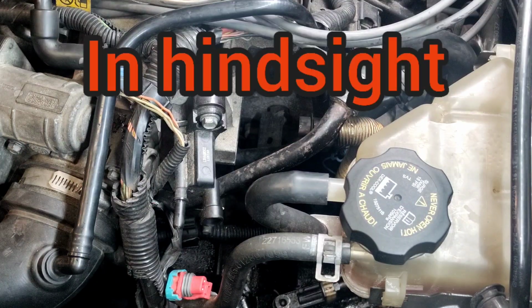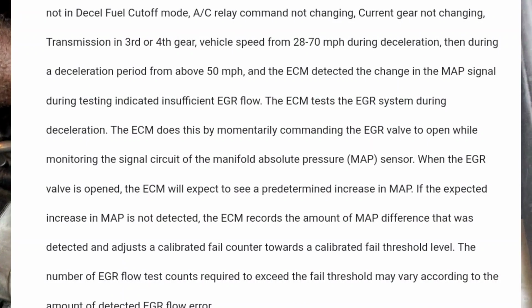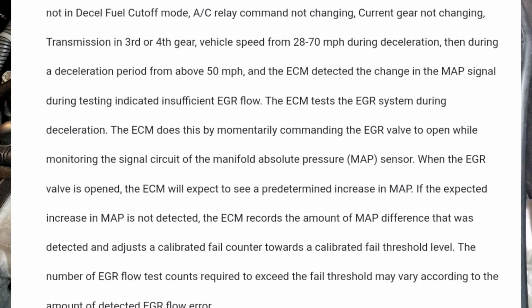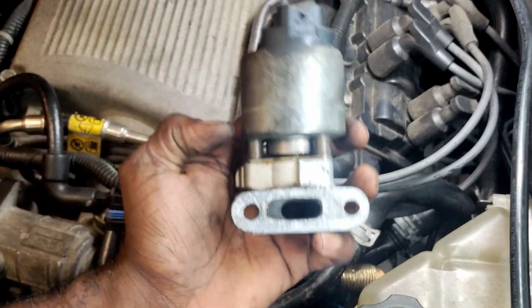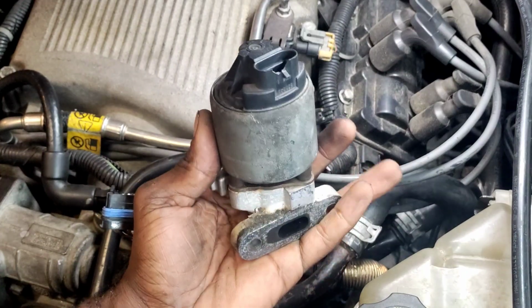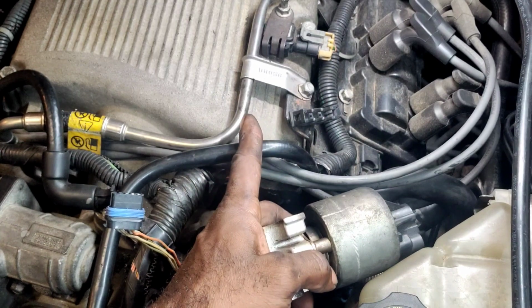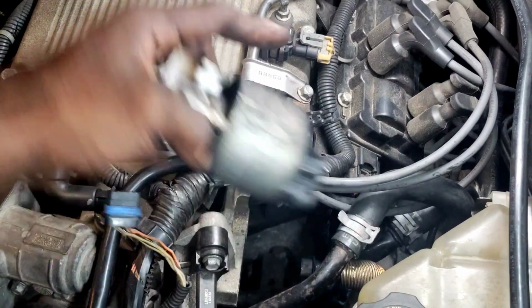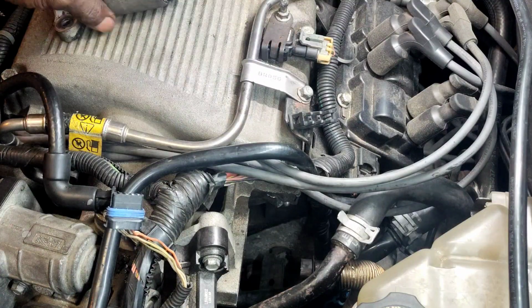This is just a change here. I already got the EGR valve off, but I'm gonna put this at the forefront. The EGR works by going into a decel state. So basically, once you let off the accelerator pedal from like a 50 mile per hour speed, the EGR valve will open. Being that the intake plenum is going to be in a deep vacuum, the MAP sensor is going to basically recognize a vacuum leak.